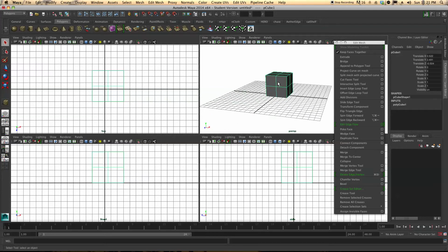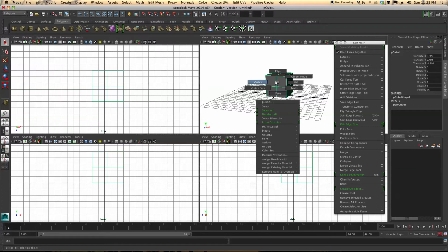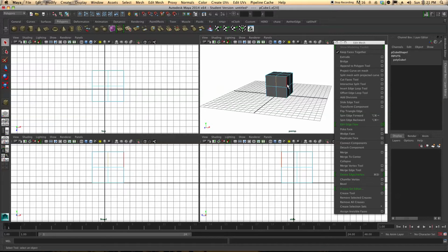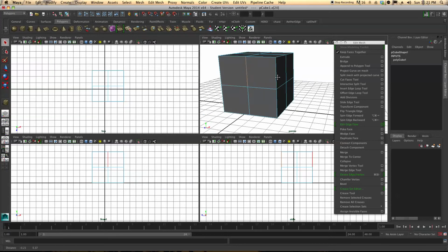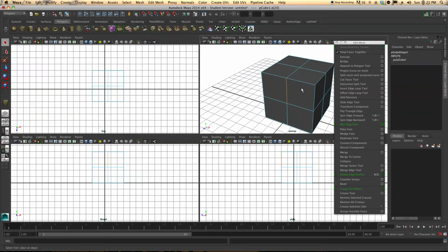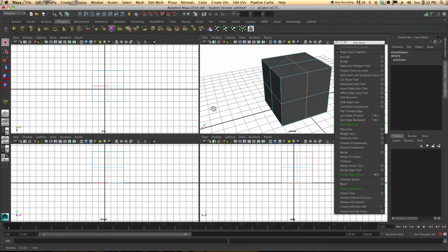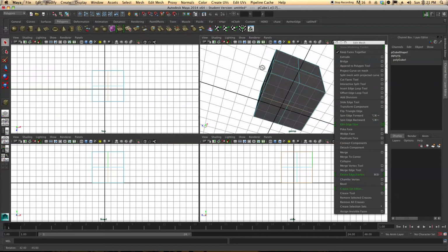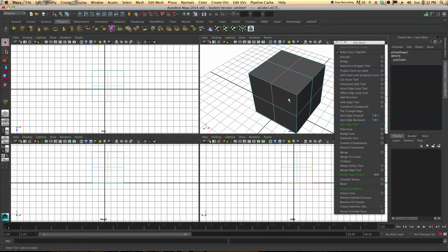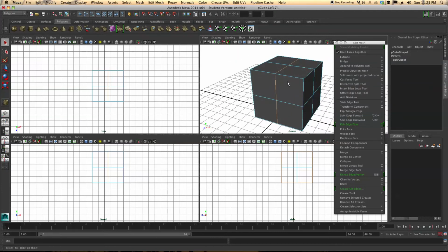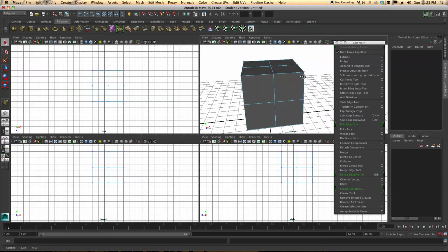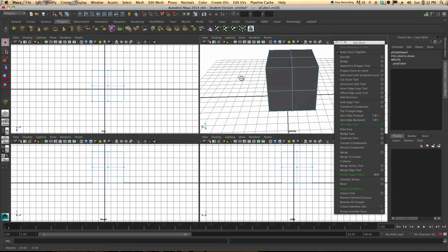So let's look at some of the basics. I'm going to hold down right click, and when we're right clicking, we have the ability to select various different parts of our model. The edge allows us to select all of the edges, the lines between each vertex. If you shift select and double click, you can fully get a wraparound. You can complete the entire continuous line. Very useful later on. Vertex is the individual point where everything meets up.